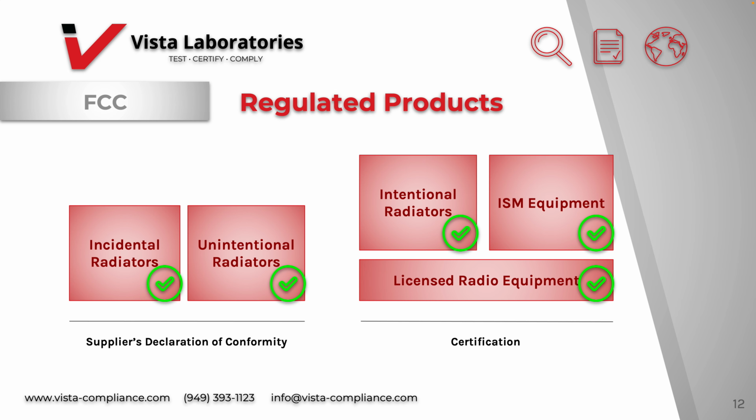So to summarize, intentional radiators, ISM equipment, and licensed radio equipment require approval under the certification procedures and are required to be tested by an FCC recognized accredited testing laboratory. A telecommunication certification body, or TCB, also reviews all of the supporting information and evaluates results to determine if the product complies with FCC requirements. Finally, a grant of certification is issued by the TCB on the FCC's Equipment Authorizations electronic system.